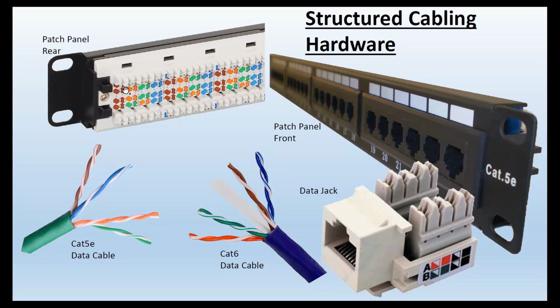So each patch panel, depending on who made it and how, you're going to have to stop for a second and figure out how this thing is done. Those color codes are going to be on the other side, and there'll be 4 pairs that correspond to that jack. There'll be another 4 pairs corresponding to another jack. So that's how things are being solved here.